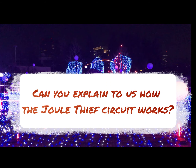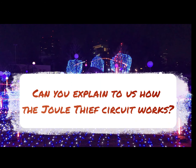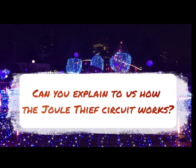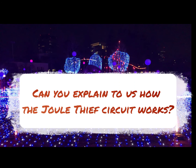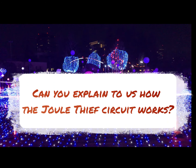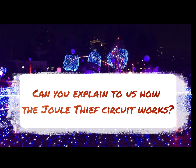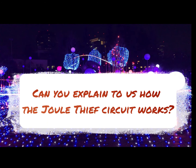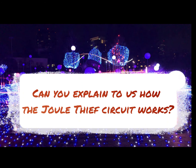After the inductor has stored enough energy, the input voltage is removed, and the energy stored in the inductor must go somewhere. The inductor starts to discharge its stored energy through the diode and into the output capacitor, which raises the output voltage. As the inductor discharges its energy, the current in the circuit flows through the diode and into the output capacitor. At the same time, the diode becomes forward biased and starts to conduct current. This allows the output capacitor to charge up and increase the output voltage.